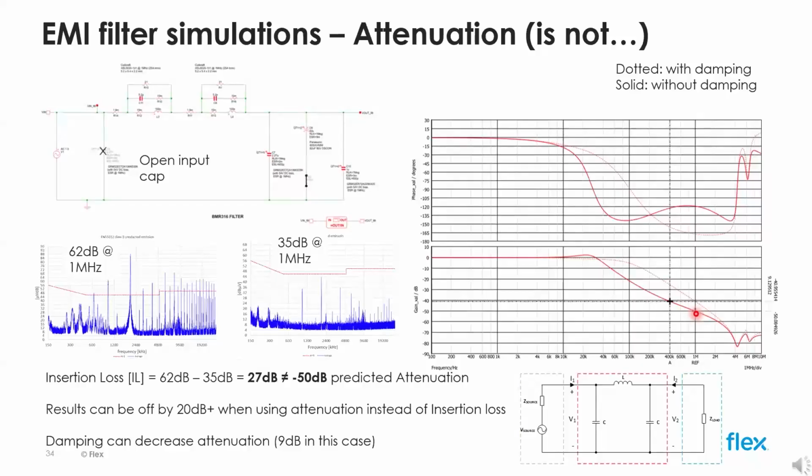We are not considering the proper boundary conditions and probably some parasitic element of the test setup, like coupling in the PCB layout, etc., not evident from component modeling alone. The next step would be to compute the same voltage transfer function with ABCD matrices and including input and output impedances and see if we get a better match with the test results.